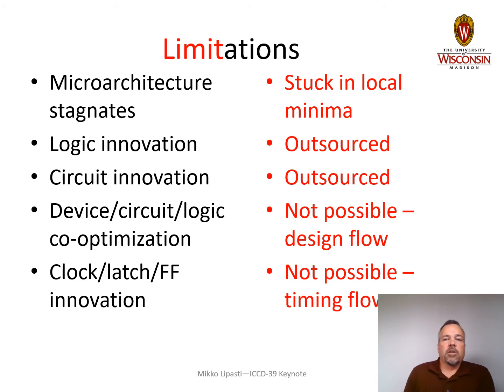We can't innovate on logic because that's all outsourced. That's done by the standard cell vendor. We can't innovate on circuits because, again, that's outsourced. We can't do any co-optimization of devices or circuits or logic because our design flow really doesn't allow that, right? All of those things are fixed, and all we can really do is map our RTL to the existing elements in our standard cell library. And then finally, any attempts to do innovative things in terms of storage elements like latches or flip-flops, or even our clocking strategy, again, very little opportunity for that. We have to use standardized design tools to design our clock trees. We have to use standardized timing closure tools to make sure that everything works correctly and doesn't have any timing